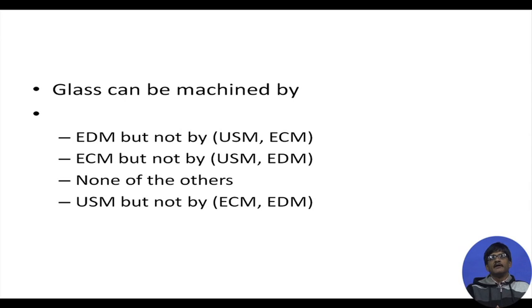Glass can be machined by EDM and not by USM or ECM. Glass can be machined by ECM but not by USM, EDM, none of the others. USM but not by ECM or EDM. So, glass being a non-conductive material, it cannot be machined by EDM or ECM, and therefore the last option is correct, which says that glass can be machined by USM and not by ECM or EDM.